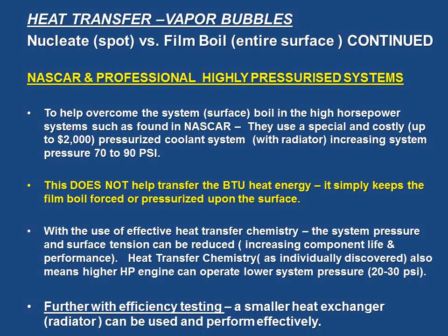Now, in NASCAR, they increase the pressure with a special pressurized system, and what they do is this increased amount of pressure keeps the vapor bubbles against the wall. See, they don't try to solve the issue with chemistry; they try to solve it with engineering, which does have some success.